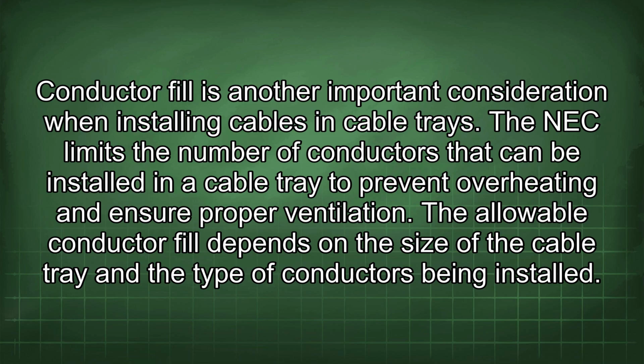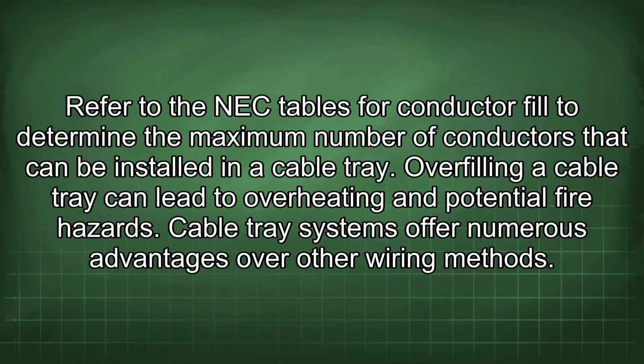The NEC limits the number of conductors that can be installed in a cable tray to prevent overheating and ensure proper ventilation. The allowable conductor fill depends on the size of the cable tray and the type of conductors being installed. Refer to the NEC tables for conductor fill to determine the maximum number of conductors that can be installed in a cable tray. Overfilling a cable tray can lead to overheating and potential fire hazards.